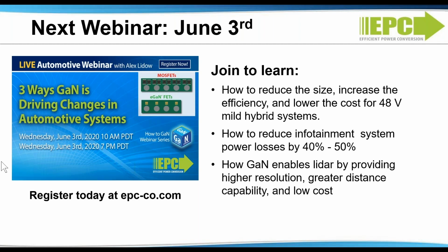What is EPC's recommendation on gate driver for the 3-level converter? So we use the teeny tiny BGA based gate drivers. A couple of good ones are the Texas Instruments LMG1205 and the uP1966.